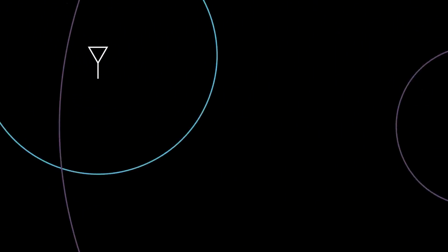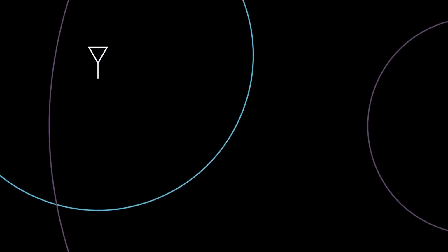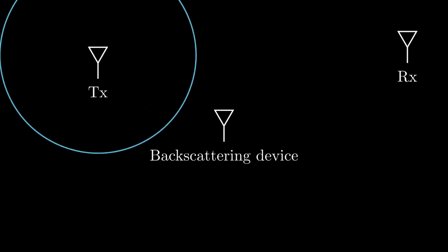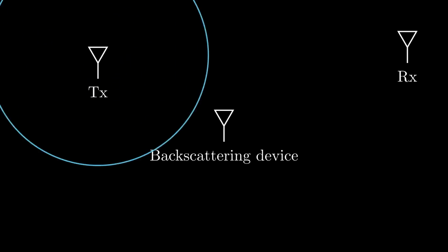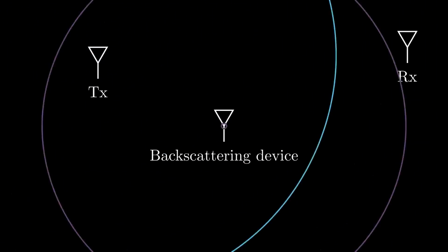Our objective is to achieve uplink backscatter communication with an energy-neutral device. Carrier suppression by static backscattering is chosen as this overcomes the self-interference. This requires 3 components in the measurement setup. First of all, we need a carrier generator. A radio signal should exist at the energy-neutral device that can be backscattered.